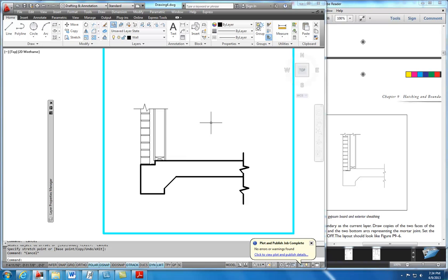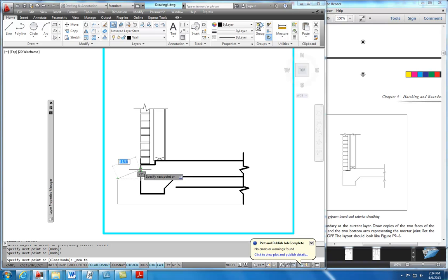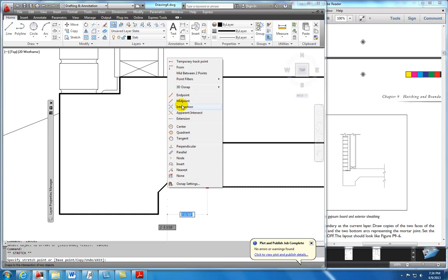And so what I will do here is I will offset 4 inches this line here to the side, and then I will just eyeball a line, we'll say right here, to about here, to here, to... Now I like to use shift right mouse click nearest so that my lines touch the other lines. And what this geometry represents is the earth and sand boundary points.